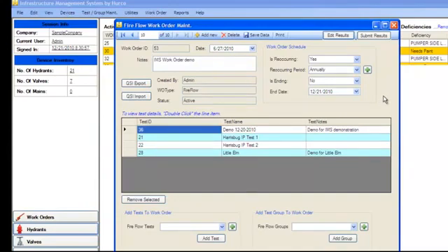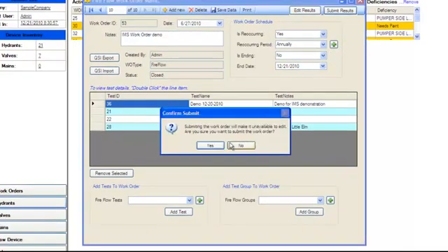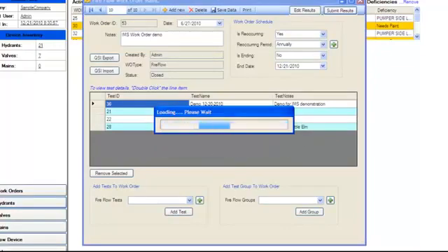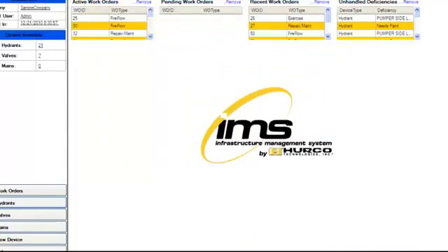Now once I've gone in and confirmed that all the data is accurate, I need to submit those results. It gives me a warning that if I click on this, I'll no longer be able to make changes. So to be sure that there's no more edits that need to be made, I'm done. I'm going to go ahead and click yes. And what it did is it just created, it saved all the test data and created reports for each and every one of those hydrants.